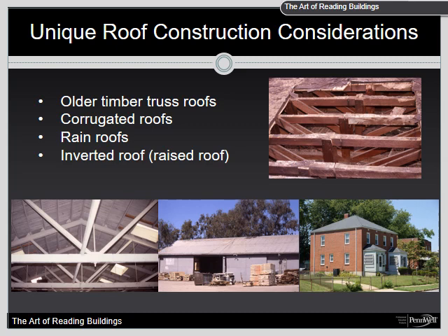In some cases, the appearance at the eave line can indicate the presence of a rain roof. Look for doubled or covering roof lines. A rain roof can add an unwanted dead load to an existing roof that can lead to an early collapse of the entire roof assembly. Rain roofs are popular on mobile home type structures.